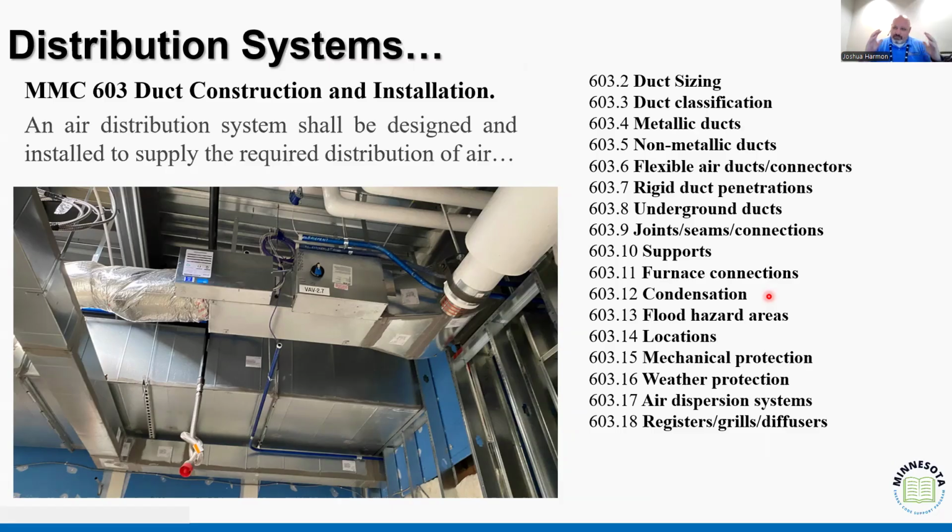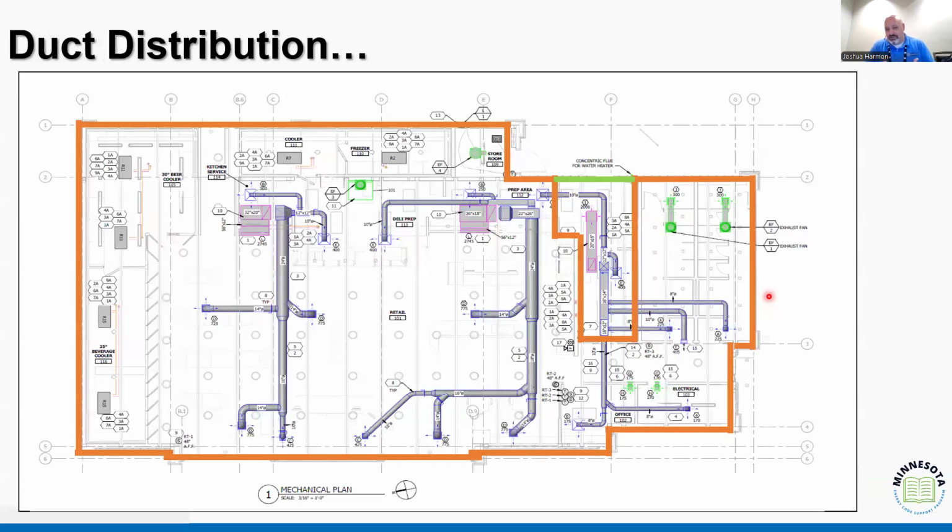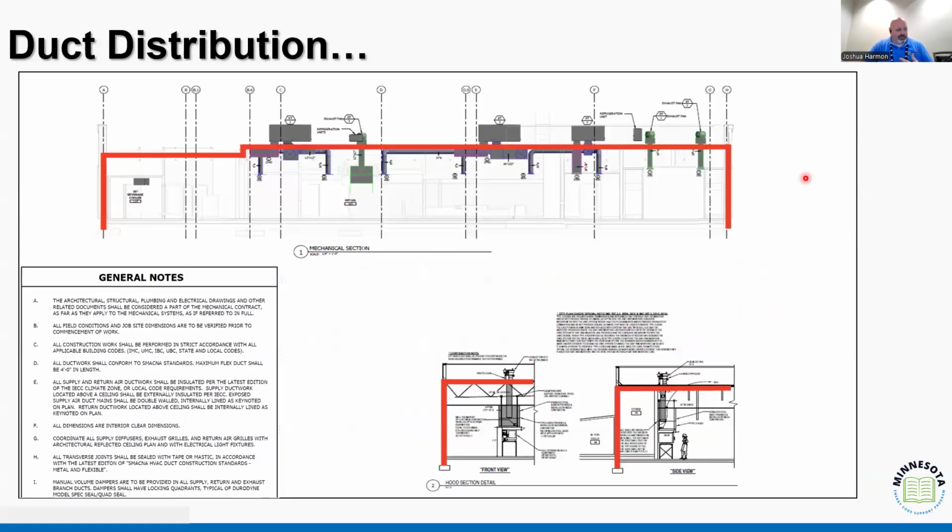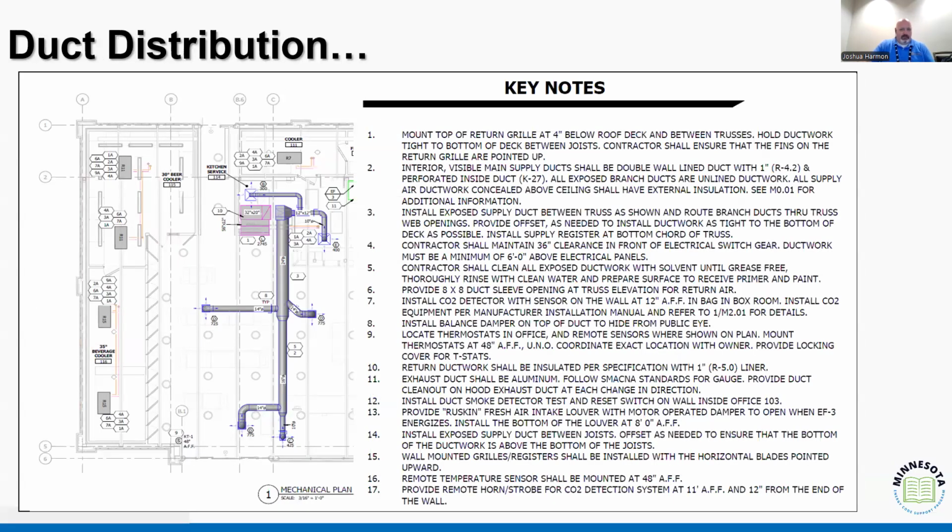So again, make sure it's properly constructed, properly insulated is a function of location, right? It's a conversation of, is it in the right spot, right? Is it inside that building thermal envelope? Over and over, we talk about it all day long, the relationship between the two. If I've got ducts that are inside that envelope, I'm not insulating because they're going to be part of that conditioned space, right? We see some notes down here about that.